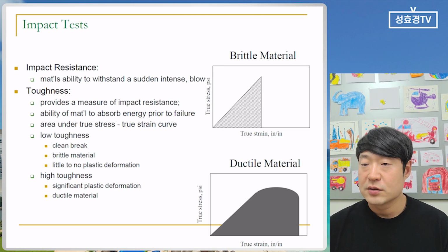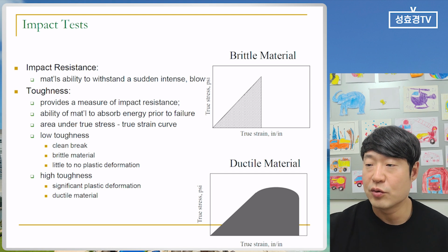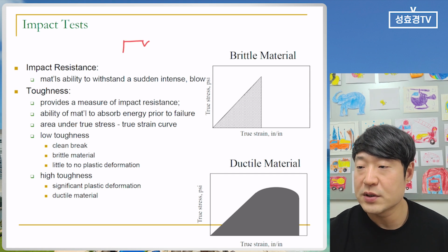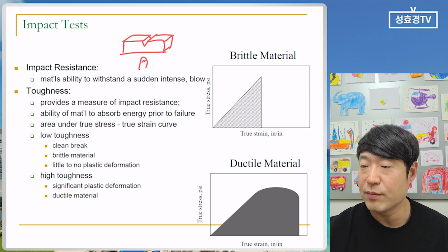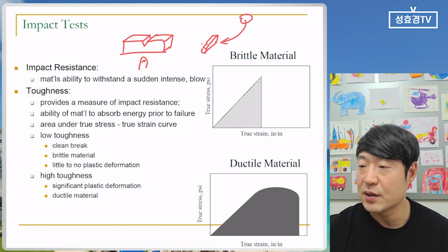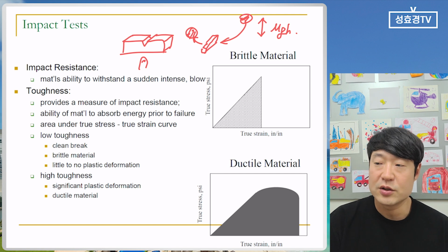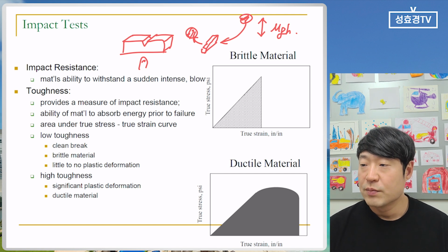And impact test. The very common impact test is the Charpy impact test, so we can draw the pictures like that. The specimen is shown like this, and there is a notch here. On this notch part, we can put the hammer. So maybe the sample is put like this. The hammer goes to this part and breaks the sample. So there is a difference in potential energy, so that we can check the absorbed energy, the Charpy absorbed energy.